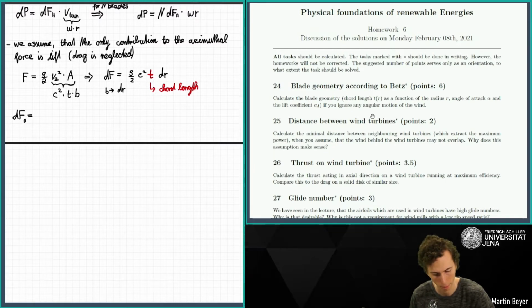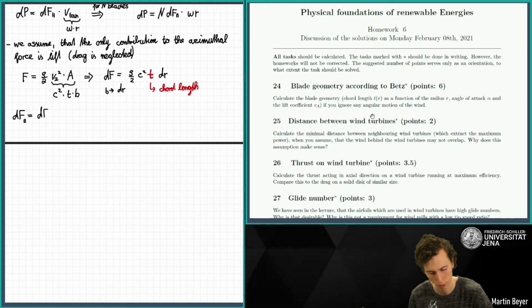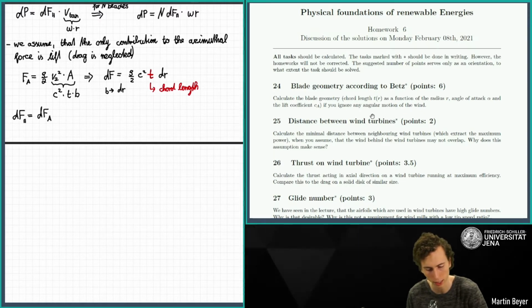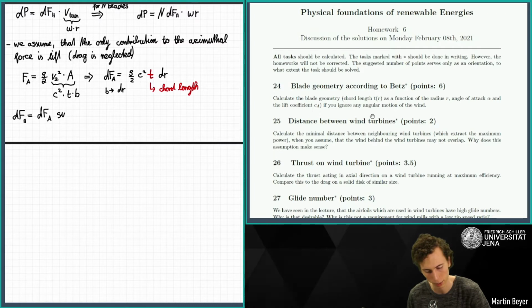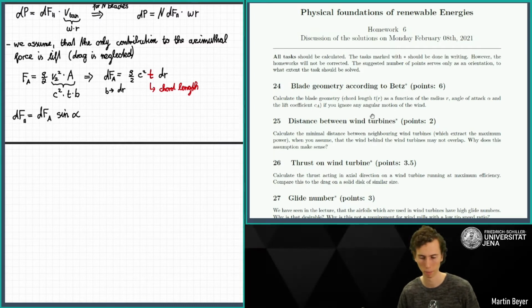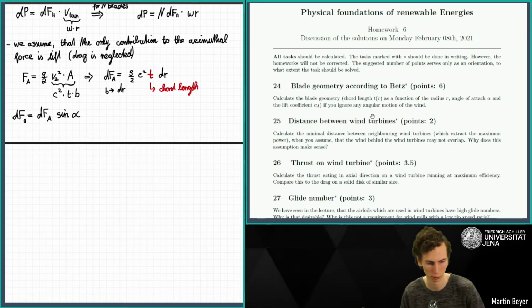So the parallel part is just the total lift part, which we should give an index A, for the German Auftrieb. And here we mean the lift times the sine of this angle of inflow, alpha. Okay, so this is not the angle of attack, it's the angle of inflow.